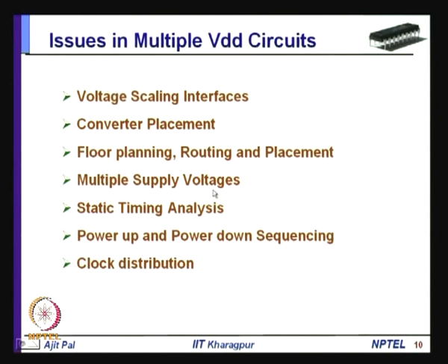Then multiple supply voltages. Here the question will arise, how many supply voltages will be used, 2 or 3 or 4. There is a trade-off between delay and the reduction in power dissipation, that is, the performance gain in terms of reduction in power dissipation versus the overhead that is increased; that trade-off has to be solved.